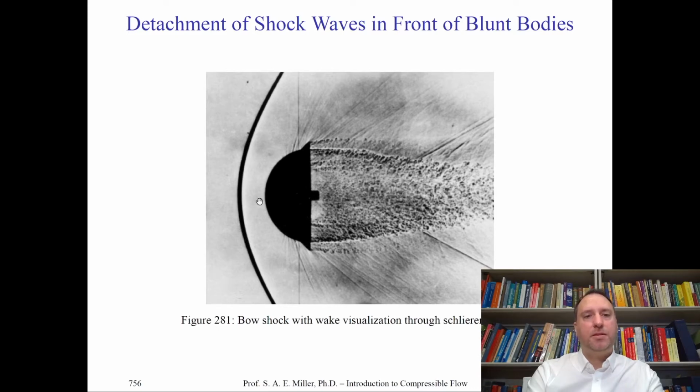Of course, the turning angle of this vehicle you might view as 90 degrees, which never has any solution of any particular set of theta, beta, and Mach number equations. This causes the shock to offset from the vehicle in front of it. So in this particular case, we might ask ourselves, how do we solve this problem? And it might be seen as rather difficult.